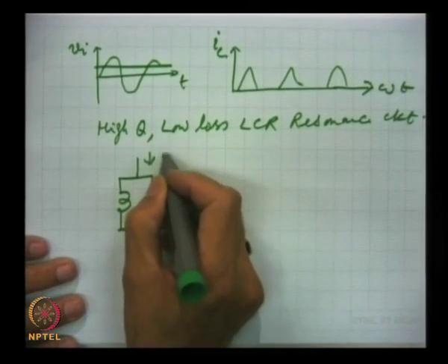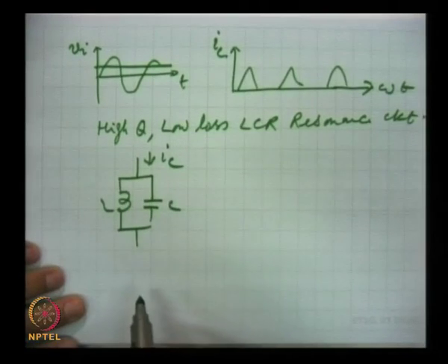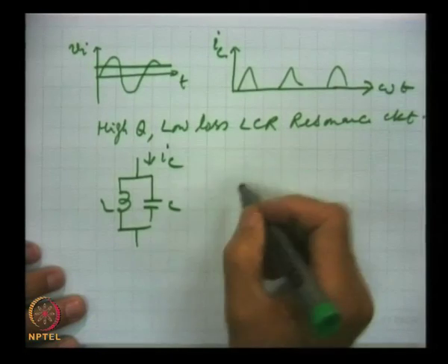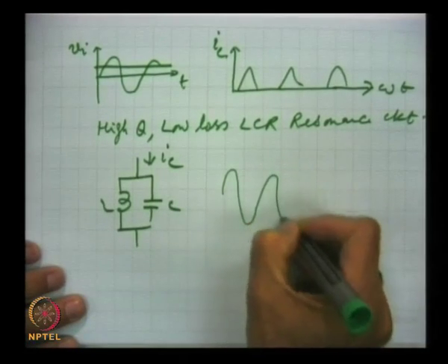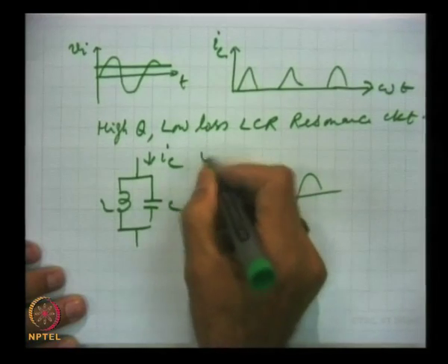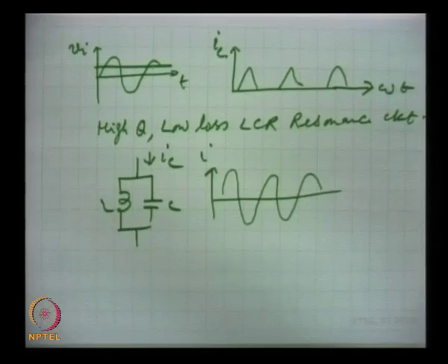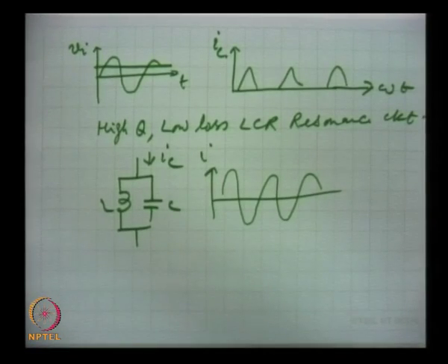When these current pulses excite this LCR circuit, then at the output the total sine wave is retrieved. The output available is this. So, why class C amplifier? What is the advantage? Efficiency. The efficiency of class C amplifiers is above 95%. For class A amplifier 25%, class B amplifiers more than 75%, and for class C amplifiers this is in excess of 95%. So, this is a big consideration, but there is a limitation.